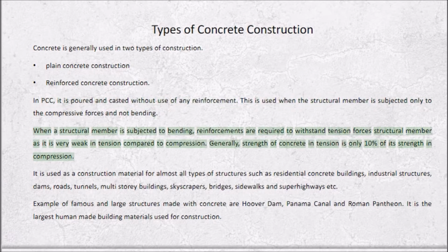When a structural member is subjected to bending, reinforcements are required to withstand tension forces, as concrete is very weak in tension compared to compression. Generally, strength of concrete in tension is only 10% of its strength in compression.